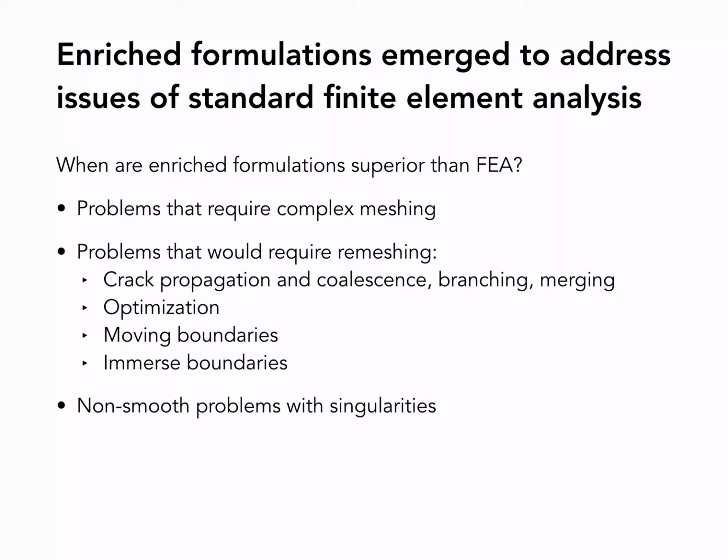If that object is very complex, creating that mesh may be difficult, especially if you're dealing with three-dimensional problems. So there is a class of methods called immersed methods, or fictitious domain methods, where you can actually take the object and just immerse it into a mesh. So the mesh is a very simple structure, and it's encompassing the object completely. Of course, it's not as simple as it sounds, because you can imagine that something needs to be done to detect those boundaries. But there is quite a lot of research on that, and there are plenty of methods. You have CAD-FEM, you have the finite cell method, and there are a few others.